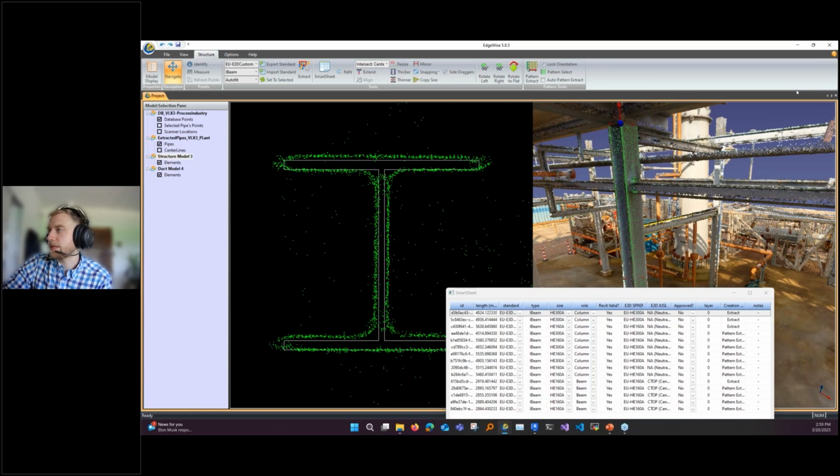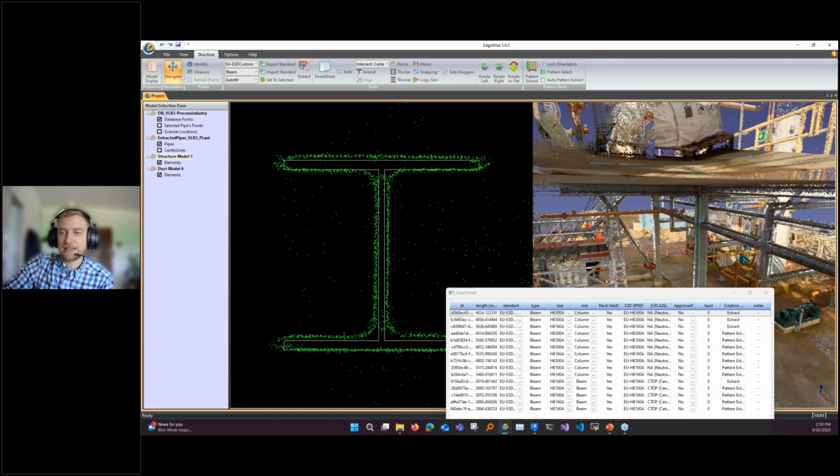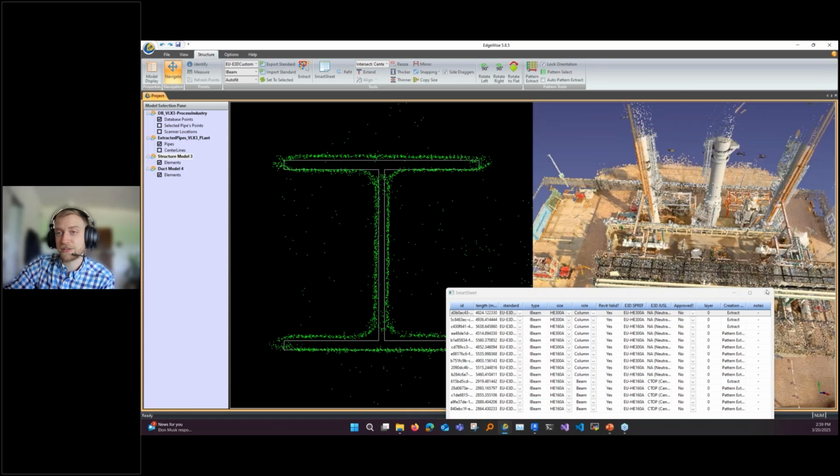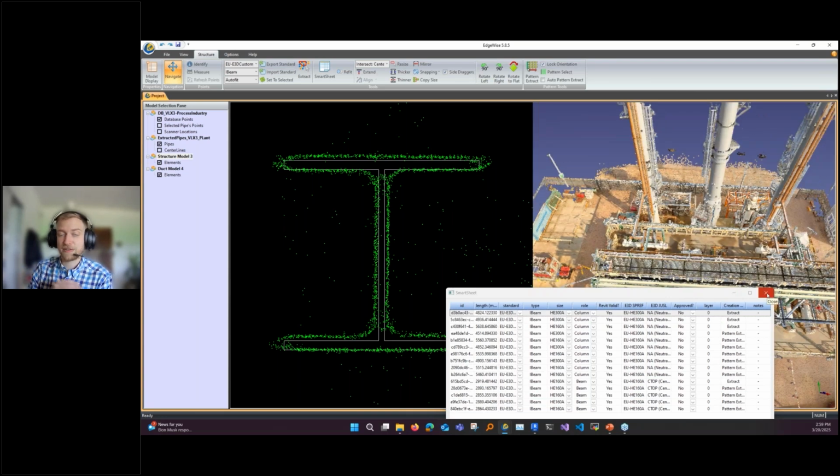Yeah, so I think Trevor already answered that. A question came in about clean and easy connect messing with settings of things. That is something we fixed a long time ago: if you run easy connect, if you run clean, if you run apply standards, and you edited an object, we do not unedit it for you. So if you edit the elbow bend radius, and you're going to Revit or to a step file, that will go directly, and applying standards or applying clean will not affect that. We leave those alone if you've modified anything inside the project.